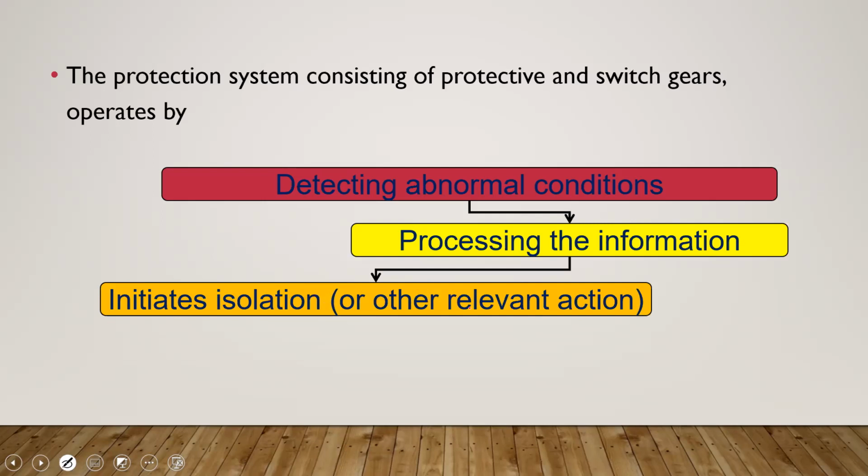So you may get an alarm from a transformer, for example. There are certain relays that instead of tripping the transformer, will send an alarm to your central control. They will see the alarm, they will know that, okay, there's some deterioration taking place, and they will have time to react, all right? So we can either initiate isolation or we can send an alarm signal.